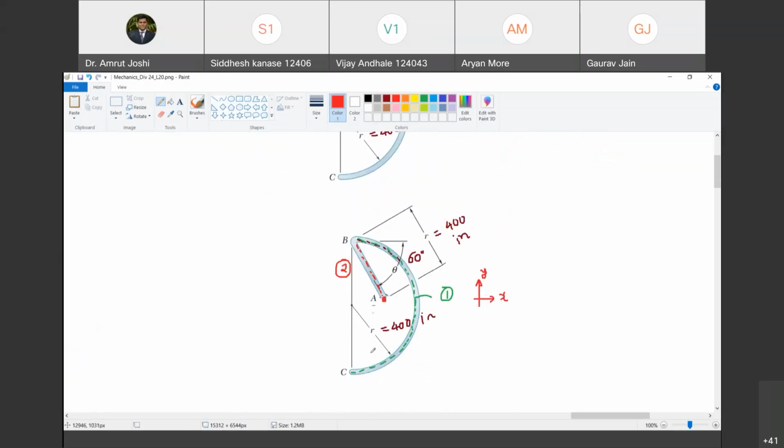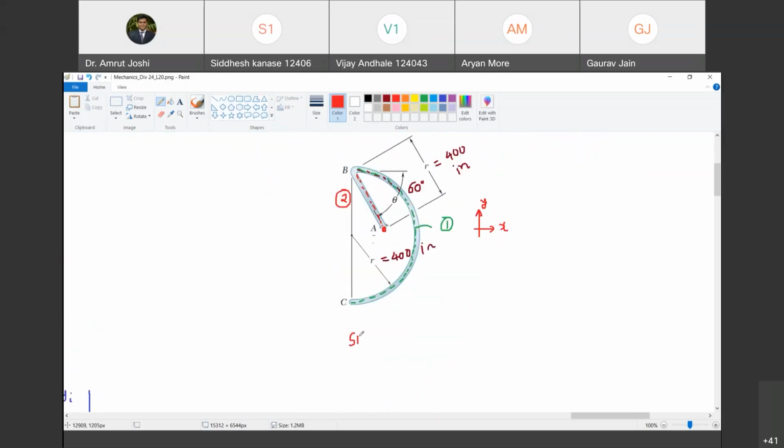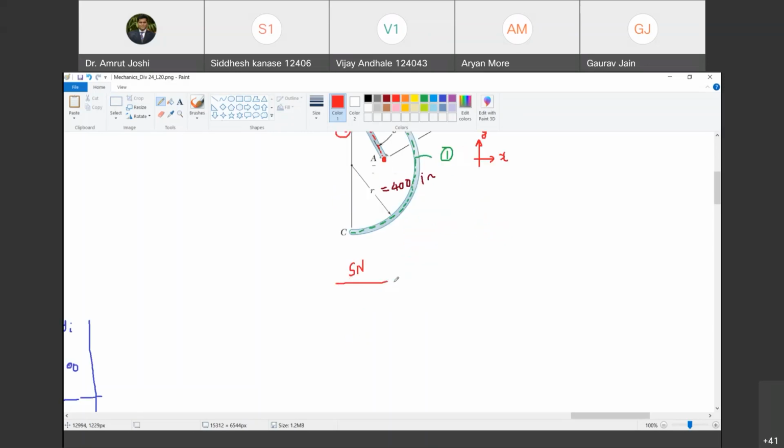The change in our approach now will be, here we write down the serial number, and then instead of areas we are going to write down lengths. Are you with me? Yes, sir. Li. Then the rest remains the same, xi, yi. And instead of ai xi, we will write li xi, and instead of ai yi, we will write li yi. Happy? Yes, sir.